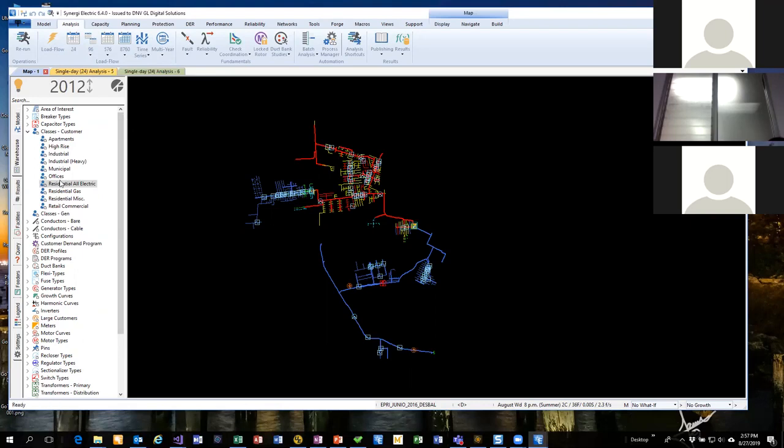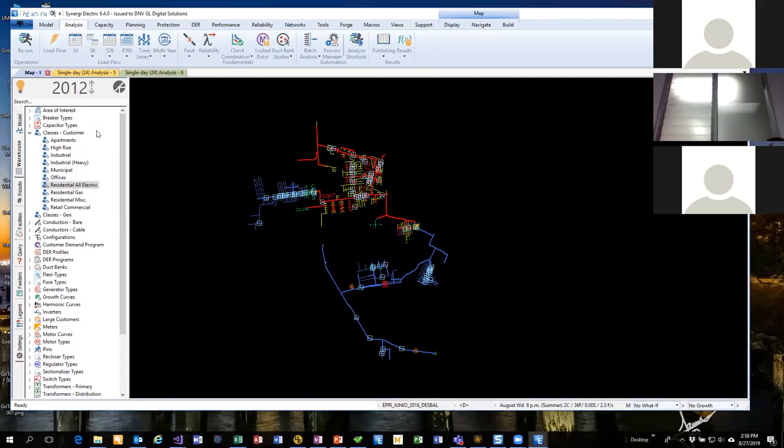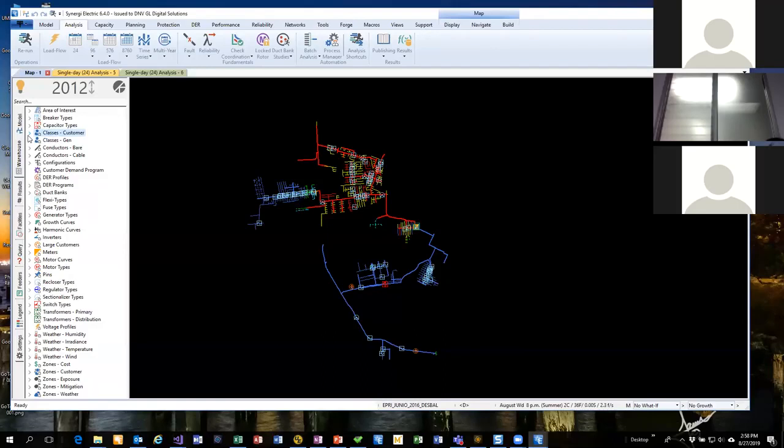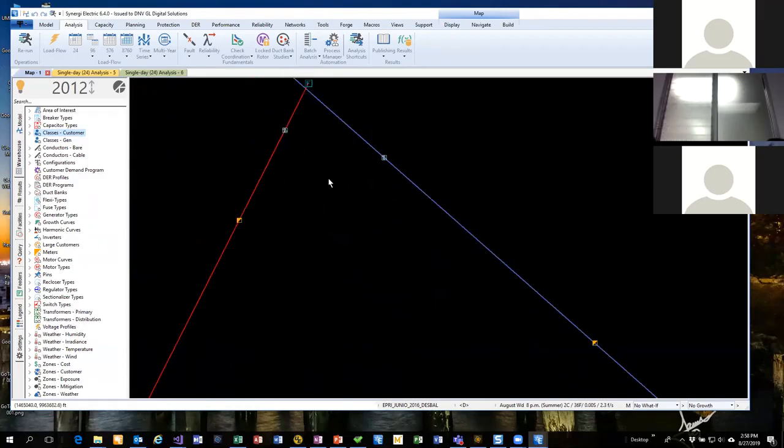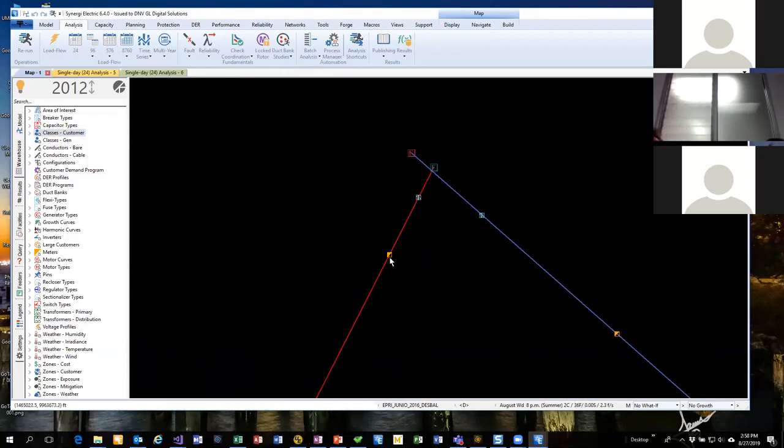You've got to collect a lot of data, do a lot of data processing. It's complicated, tedious work. You all, a utility your size, might have economists and statisticians who do that kind of thing. I see that at big utilities a lot. And so you might have those capabilities. Even if you do, it's still a lot of work to get that information from those groups into the engineering model. So what we did was put this data lake tool in there so that you could import feeder demands. Each of these feeders has a meter sitting right here, and this is where you would put in demands for load allocation.